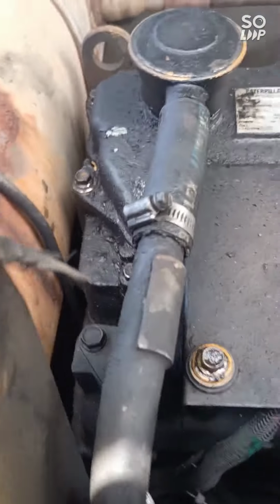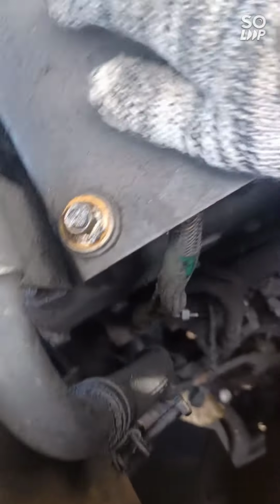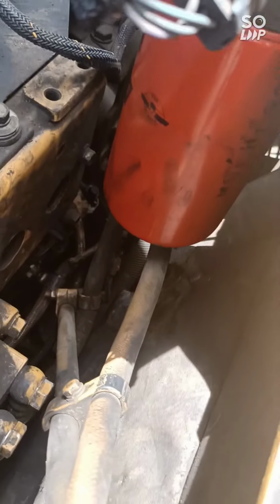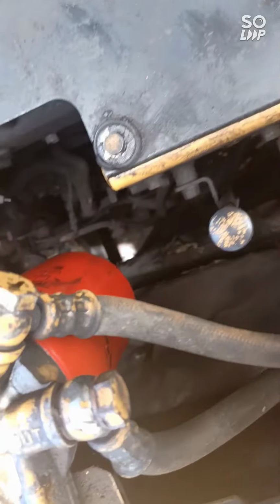Here at the engine bay, we can look for the engine speed sensors. The primary was located at the flywheel housing, and the secondary was located at the engine's injection pump. So the primary one was located at the flywheel housing, so we're going to look for that.